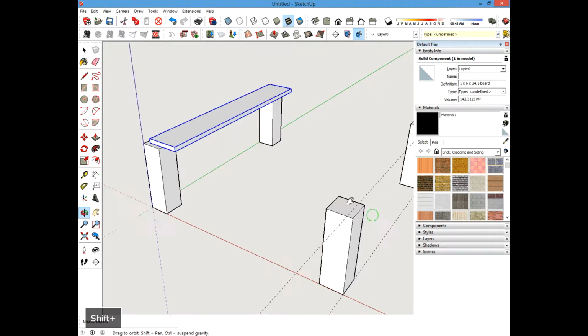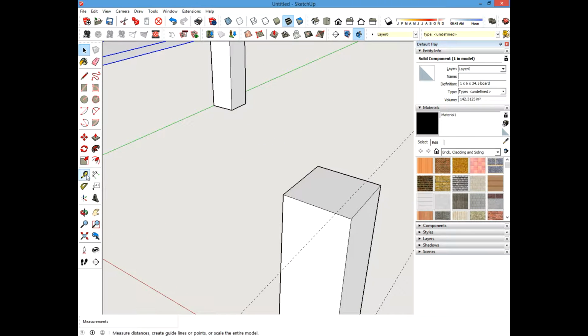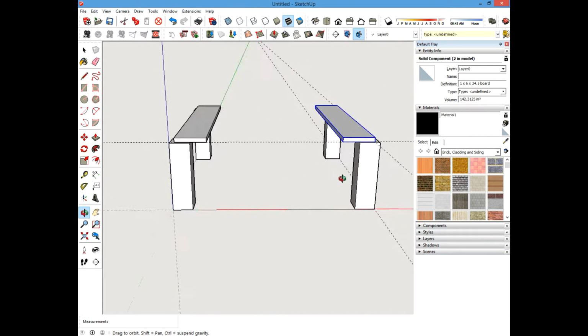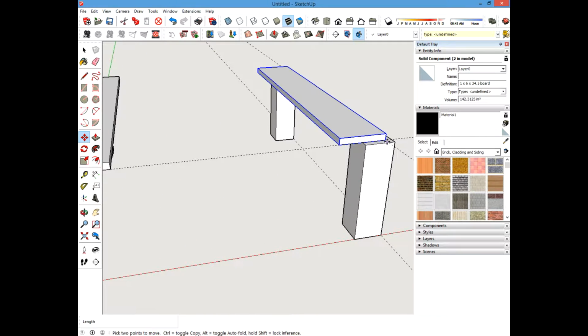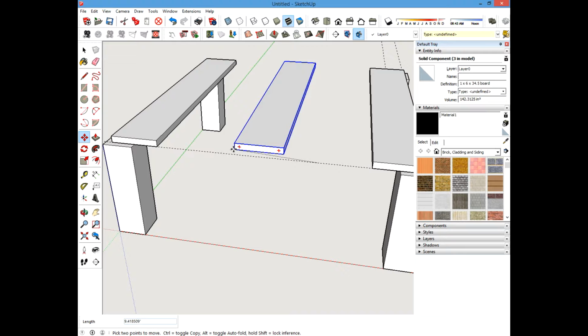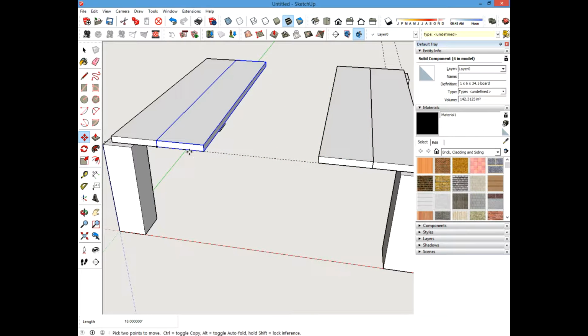So I'm going to need another snap line down here. I know I just erased it. Let's put that back in. 0.75, enter. Okay, so now let's go ahead and grab this corner here and hit control, and we're going to line it up here. And now similarly, I'll grab this corner here and control and line it up there. And let's grab this and control and line it up there. And let's just repeat the process. We'll see how many we can fit in here.